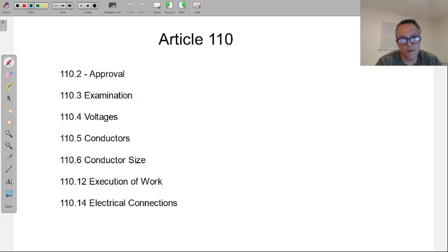I would say there are a few products that this comes up with, switches as well. When we buy switches, it's also something that we have to keep in mind anytime we buy anything. This, I was going to say, more so falls when you get into the world of industrial fuses, because fuses are one of those where there's two types of ratings. You either buy fuses rated for 250 volts or less, or you buy fuses rated for 600 volts or less.